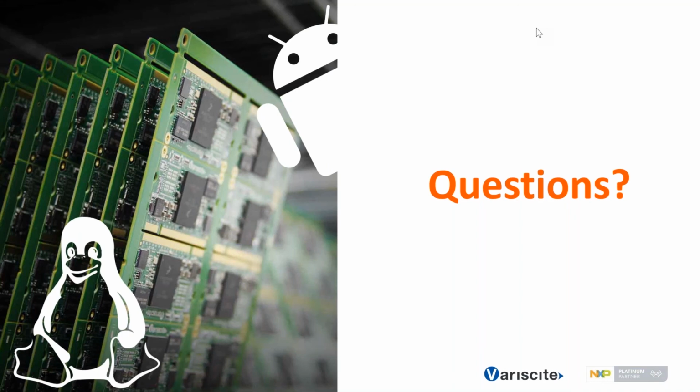Okay, and another one for you, Pierre. Do you have examples of Docker on i.MX 8 SOM? We have a dedicated section in our wiki explaining how to enable Docker and how to run a Docker example, and we provide a specific Docker example, for example, to run a server application. We are increasing this section with new graphical examples, and it's mainly on the wiki in a dedicated link for each SOM that supports Docker.